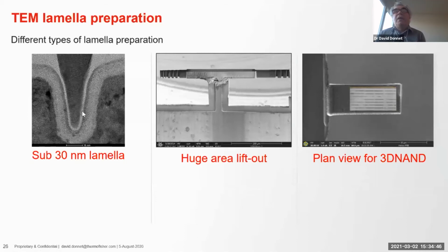So high quality lamella is possible, but not if you require high throughput. So if you need to do this 24/7, still stick with the gallium. But if you need occasionally to make a high quality lamella, plasma FIB can do it.